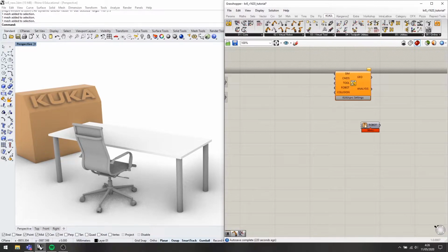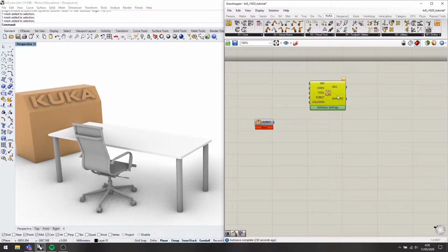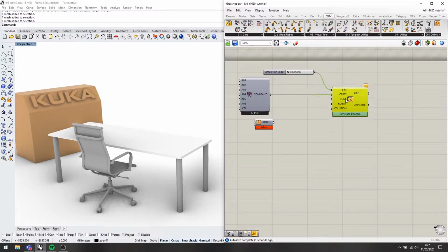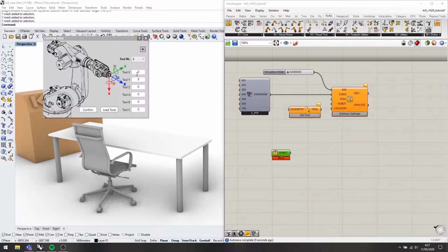We're going to grab our Kuka core component. I'm going to set up our simulation slider as always to be from 0 to 1 with a few decimal points. Temporary 6-axis just to make sure everything looks right. Set up our custom tool already. Can set tool. I've already done the tool calibration. 1.4, 0.25 and 109.78 along the z-axis. Confirm.